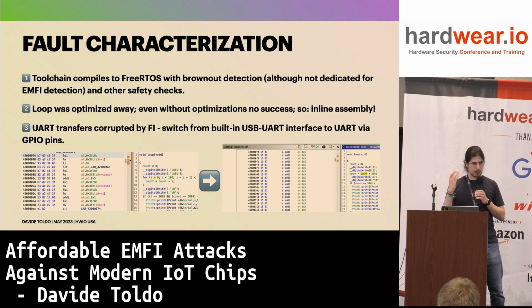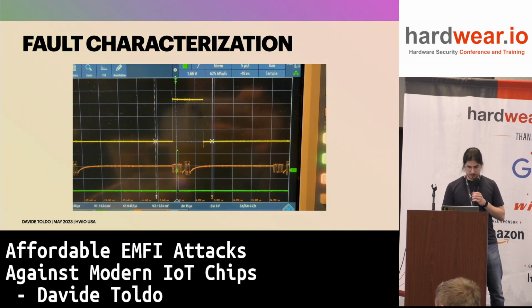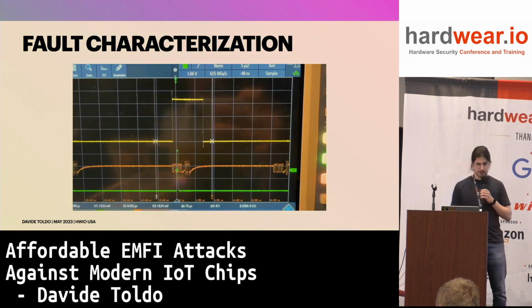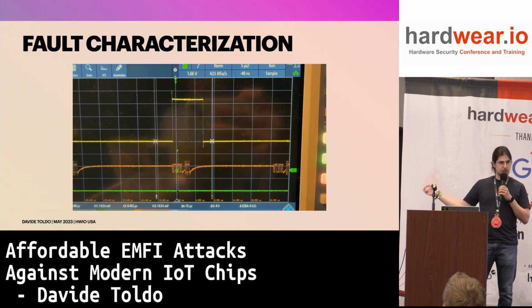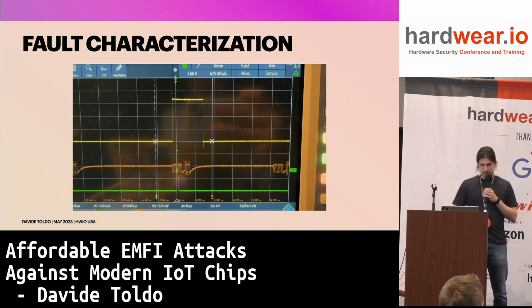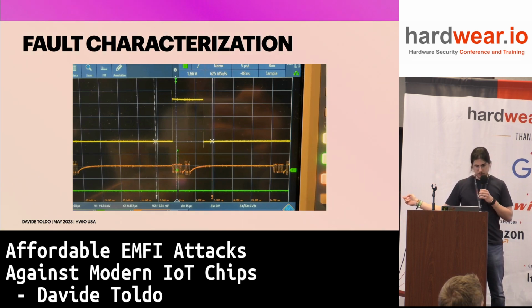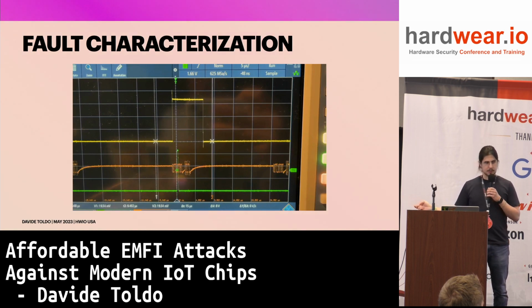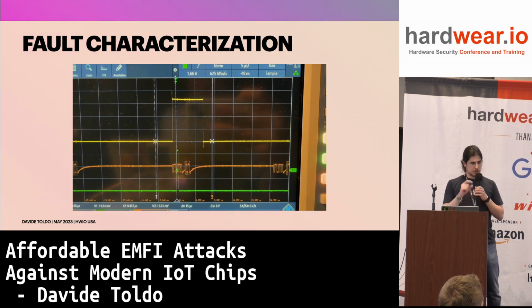As we can see here, I have my GPIO pin high on the top, and on the bottom line I have the glitch pulse. It's narrow, but I hope you can see it. And the USB packets are just in the middle, fully out of place, and it was corrupting my communication. Yeah, many pitfalls.